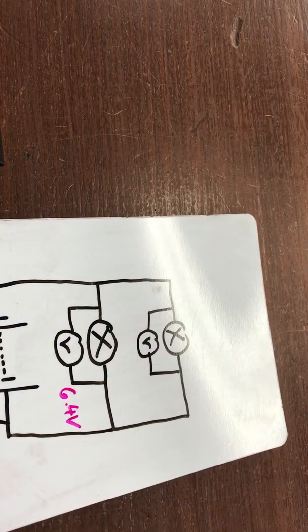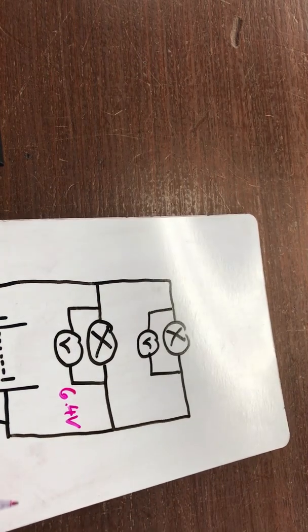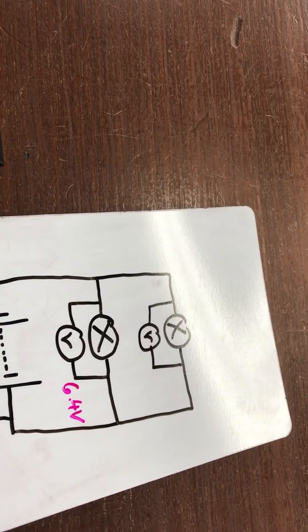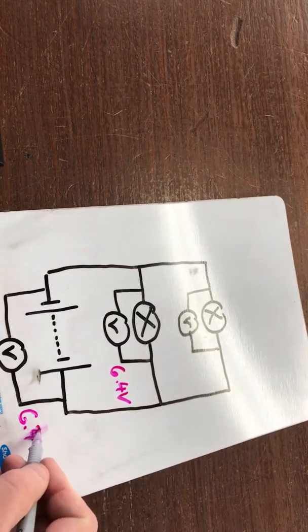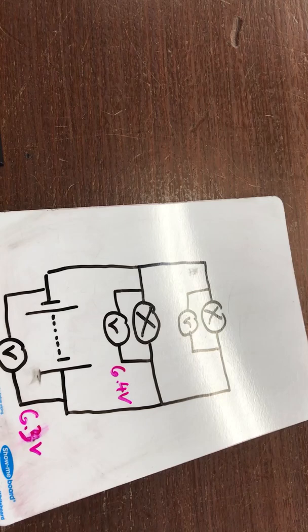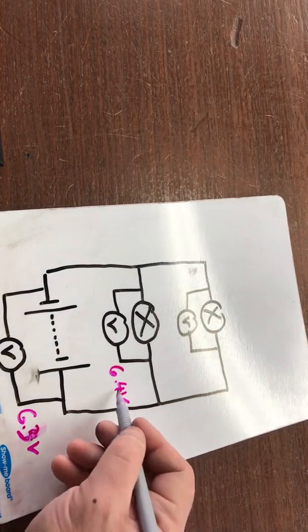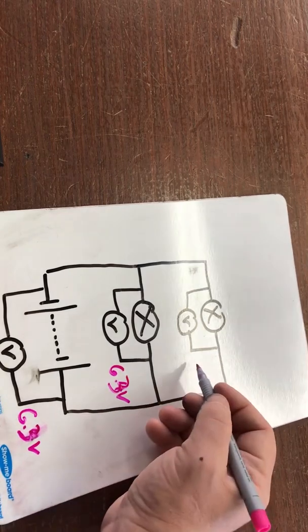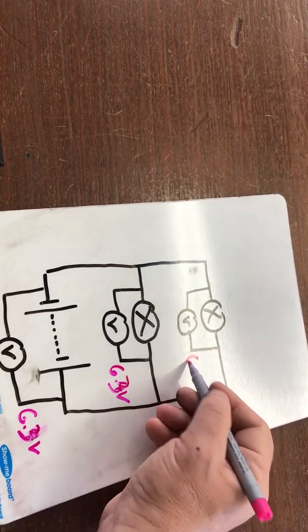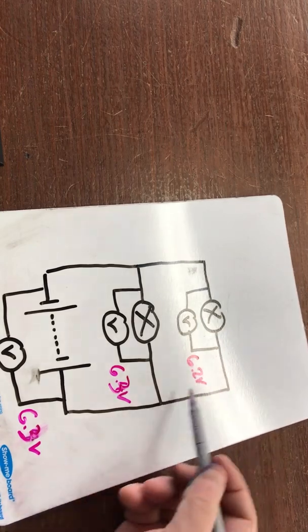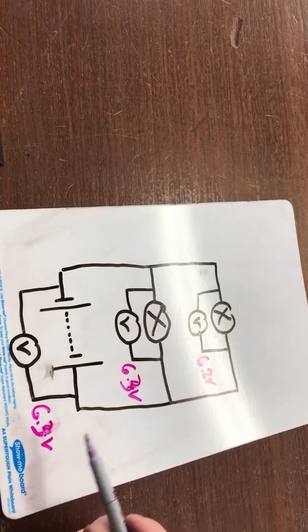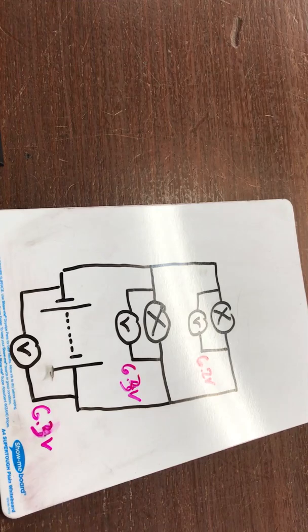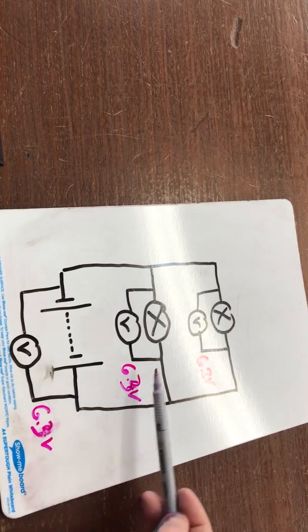And what we did when we measured this is that actually this voltage here had dropped slightly. So this was now 6.3 volts. It was slightly smaller. This one here got 6.3 volts. And this one here got 6.2 volts. So it got slightly less, a tiny amount less. It's probably due to the extra wires it's got to go through using a little bit of the energy. But what you can see, hopefully, is that the voltage is very similar from the power supply to this lamp